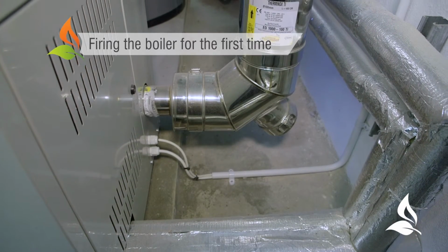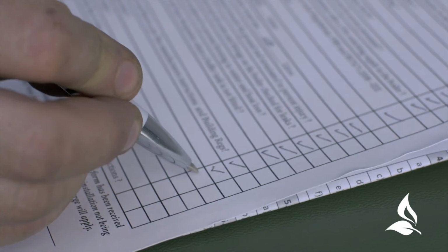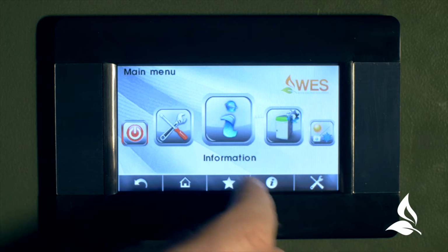By now the installer will have connected power to the boiler and have the unit plumbed. The pre-commissioning checklist will have been completed and the manufacturer will have reviewed the checklist before issuing the unlock code. Turn on power to the controller by the red switch by the electrical panel on the left hand side of the boiler. The controller will be in the locked position and an alarm will appear.